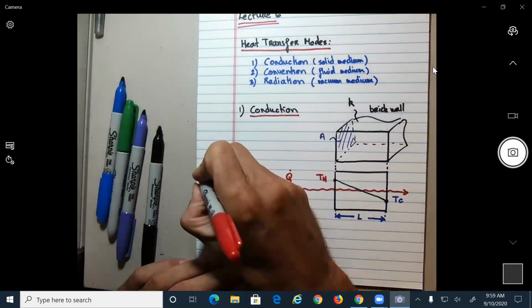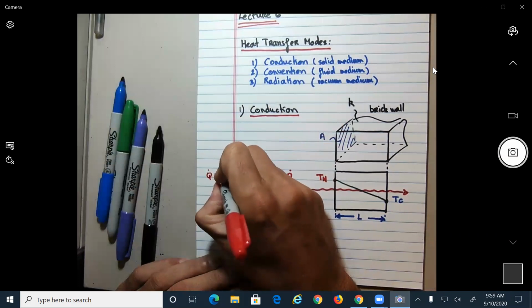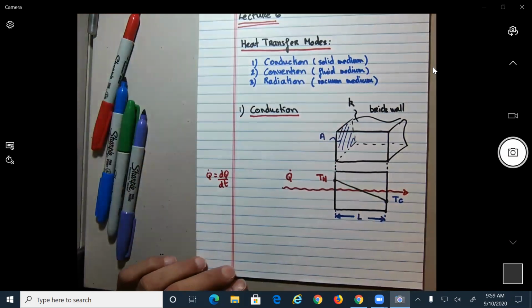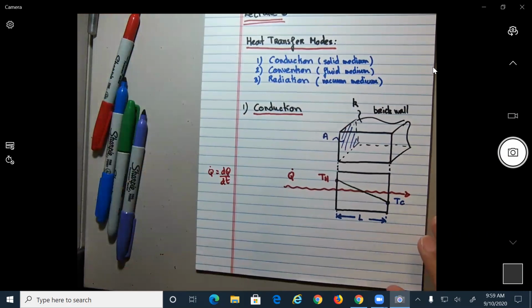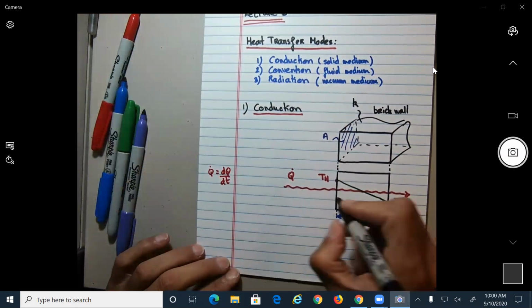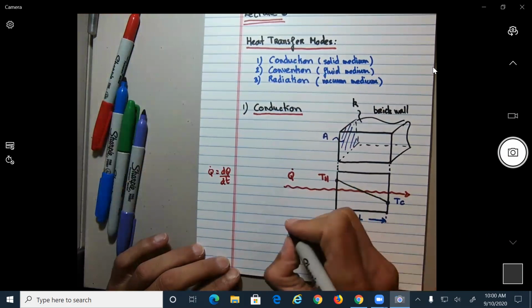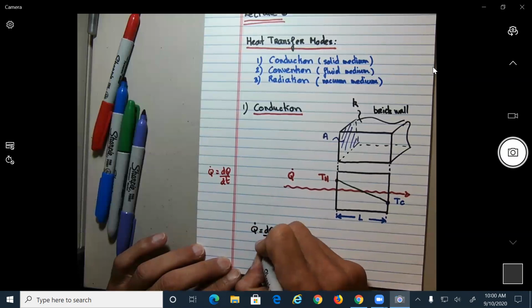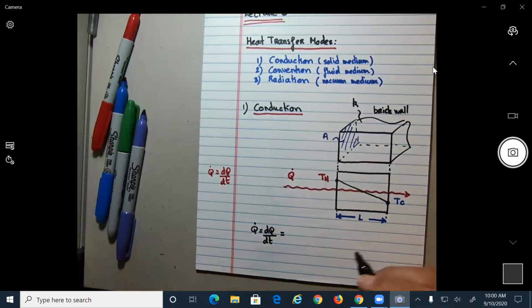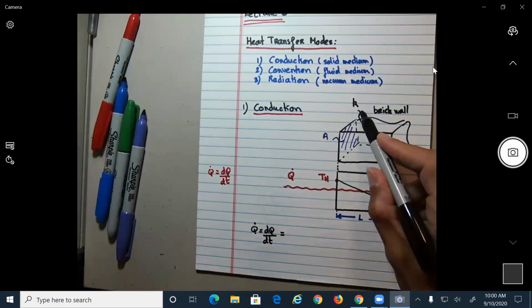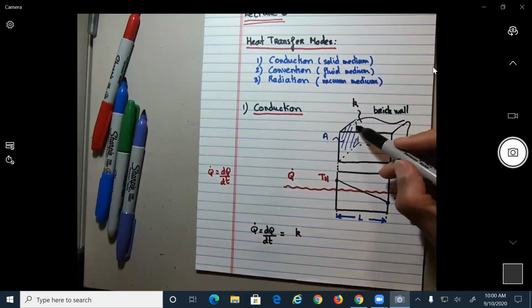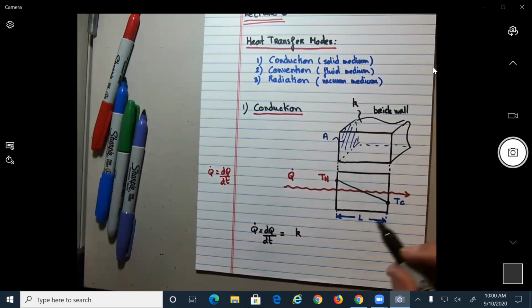Okay, so Q dot here basically means what? dQ dt. All right, so the conduction is defined by what? So this Q dot is equal, if you want, dQ dt. I'm going to redefine that. So now the heat conduction needs to be related to the material, which will be K. Also, what's going to affect is to know how much surface is being exposed to the heat transfer, A.